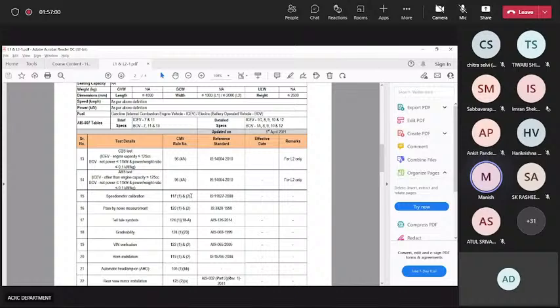So the first 3 characters will be your WMI code. The remaining 14 characters you can define as per your vehicle color, vehicle capacity, vehicle model, and vehicle manufacturing date, month, and year. All those things will come under the remaining 14 characters, and the production serial number will be around 4 to 5 digits. So that definition has to be submitted, showing how you are going to produce your vehicle and how you are going to identify your vehicle, which batch is produced, and which vehicle model is produced.